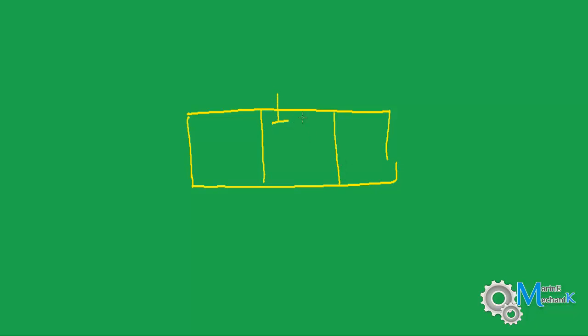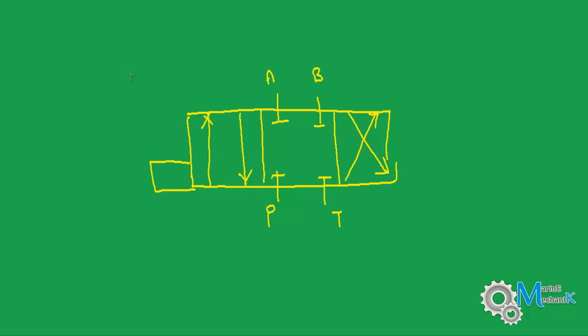You have the 3-position control valve. You have the ports here. Pressure, back to the tank, port A and B. You had the cross, which we have seen in the last slide, and now we have the parallel ways here, and you have the actuating lever, and you have one more actuating lever on this side. I'm sorry, it doesn't come straight. Now I'm going to add the spring here.